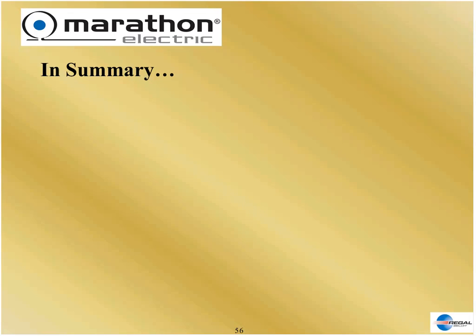Summary. My summary is we're going to take a wave from the utility, single or three-phase. We're going to capture it in a circle in our stator. We're going to put strategically placed coils. We're going to produce north and south poles, up and down, up and down, up and down. We're going to put a rotor in the center. The rotor is going to chase that curve around.